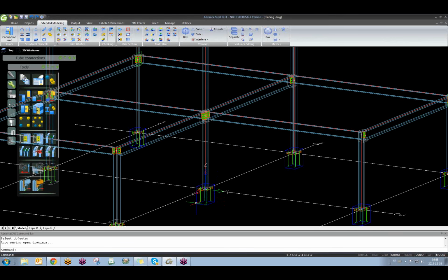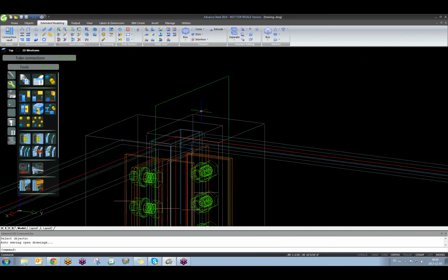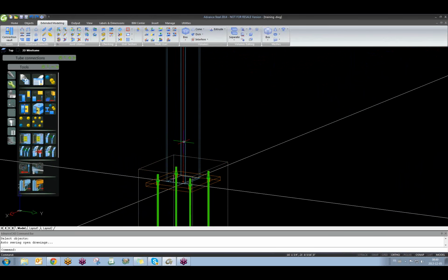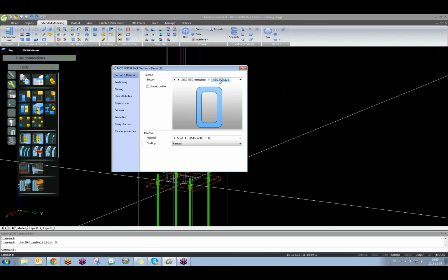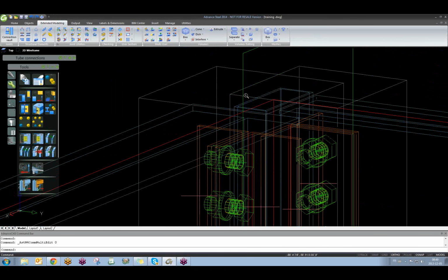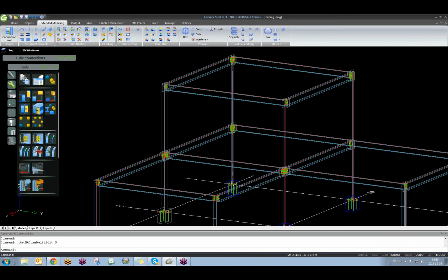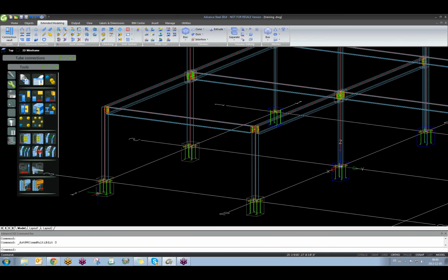it will put a blue box in the situations that are different from the master connection. Like for example, the master baseplate is connected to an HSS A686 by 1/4. If, like for example, in here we have an HSS, but it's not 86 by 1/4, so it will be a blue box. The blue box will only show you that this connection is controlled by another connection, but the situation is not really the same. But it will control it.